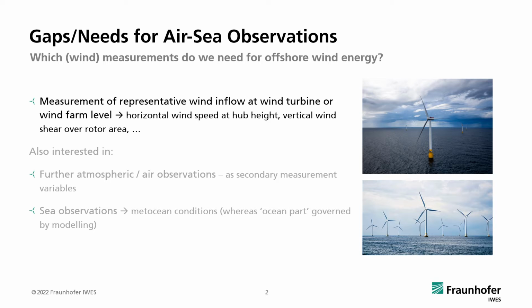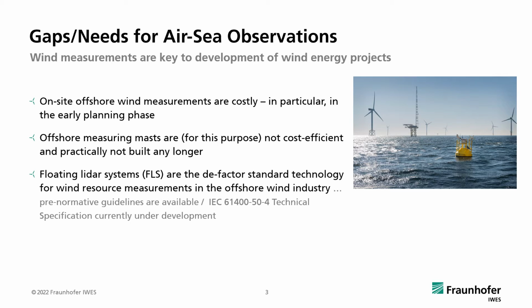Also, sea observations are of interest. Normally, they are part of the so-called mid-ocean conditions, which are assessed for site suitability studies. Here, however, we can say that the oceanographic parameters being part of the mid-ocean conditions are normally governed by modeling activities. So they are modeled. Measurements or observations are only used to calibrate the models, which is exactly the other way around for the wind part, where the project development really relies on on-site wind measurements or observations, at least for a shorter period. So we can say that the wind measurements are key to the development of wind energy projects.